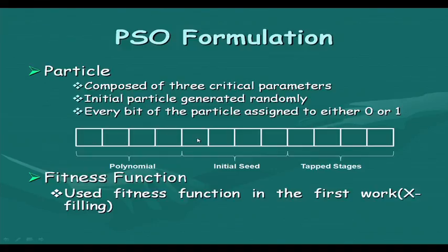Next, I need to specify the initial seed, and again there are n bits. So these n bit values can be fed here. This is the initial seed value, the value with which the LFSR will start functioning.